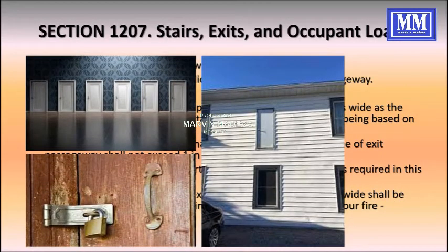Also here, the section we have here the doors. Exit should not go into this. So we have here in the first figure, we have to choose which door is the real exit. Exits should not be padlocked. It should be used for emergency exit, not to padlock it. And also, an exit should lead to a public way, but not into an area where the people go to and will fall to the ground. So this is not a good example of an exit.